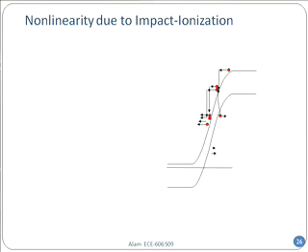It gets 3/2 the band gap, approximately. Then these 2 scatter with 2 more electrons from the valence band, and get their friends up into the conduction band. Now I have 4 electrons going. And how many holes? I had 1 from before. This time I have generated 2. So I have 3 electrons, 3 holes going.